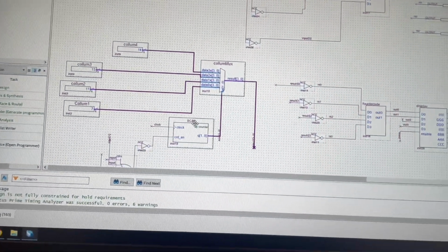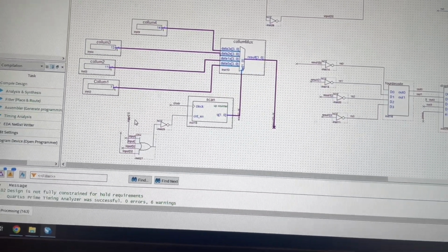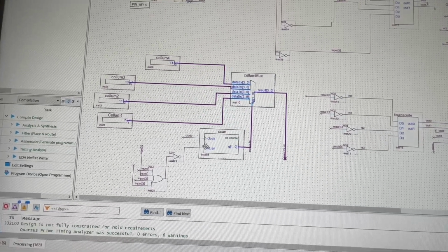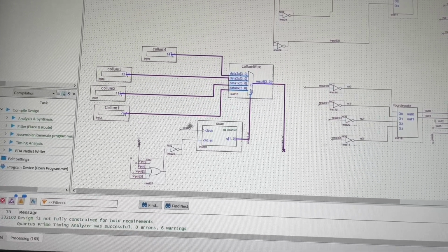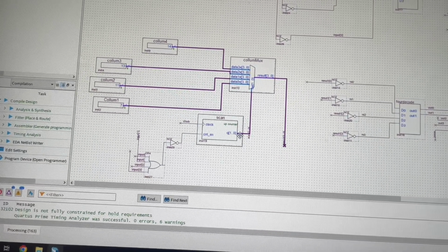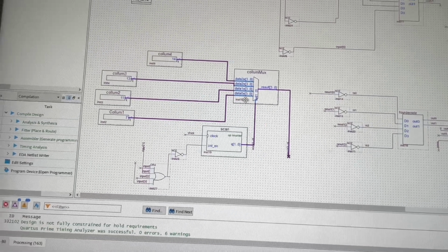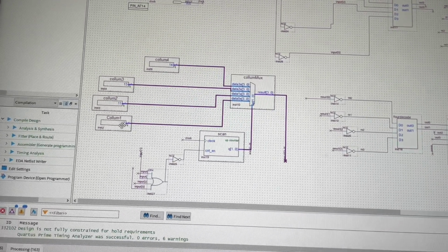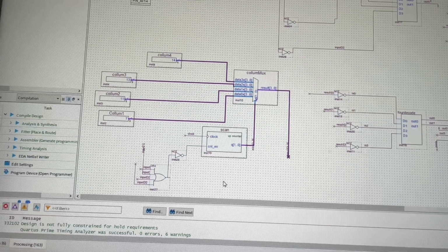Okay, returning back to press as seen here, when a button is pressed, either one of these will make this a 1, making it a 0. This stops the scan, which is scanning at the rate of the clock, going from 0 all the way up to 3, or 1 to 4, scanning through all 4 of these. This stops the scan at the correct one of these columns, which displays a 1.